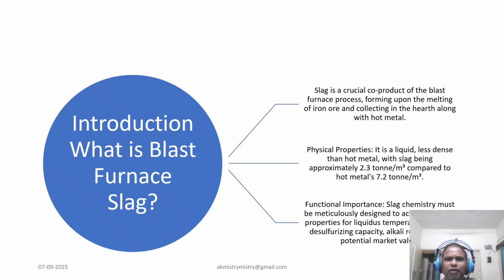Now coming to our slag forming components, that is the gangue inputs. Here we can say that the primary source of slag is the gangue material found within our ferrous material, that's our iron bearing raw material. These include first, lump ore, natural iron rich material that contains acidic gangue components like Na2O, SiO2 or Al2O3.